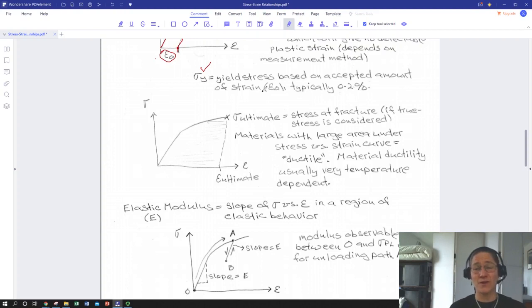So our very strong materials tend to be brittle, which means they'll behave elastically right up until the point that they break. For that, we'll look at tested empirical values for ultimate strength, and this will typically be ultimate strength in tension, which tends to be the lowest.